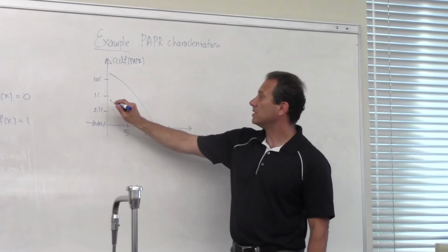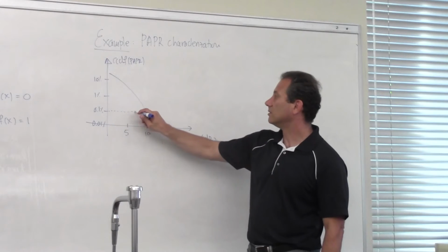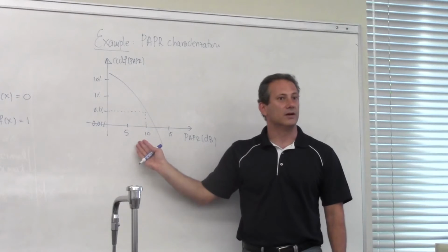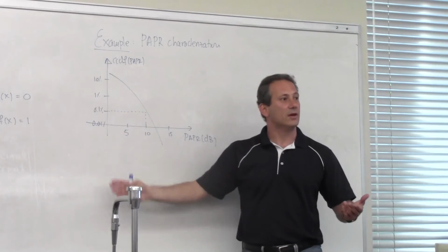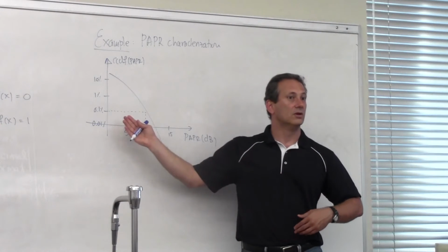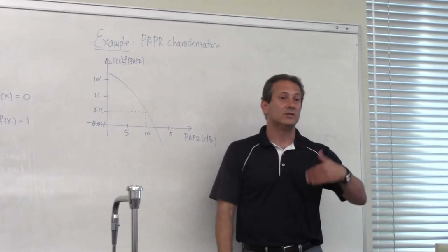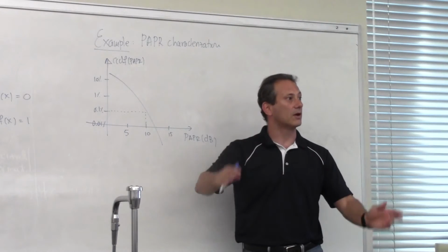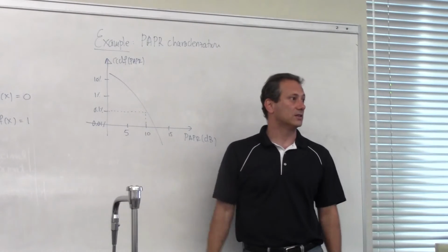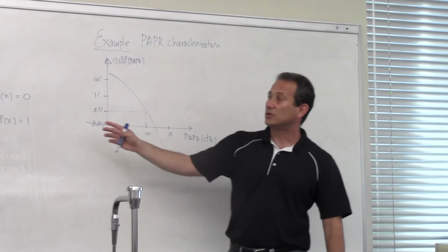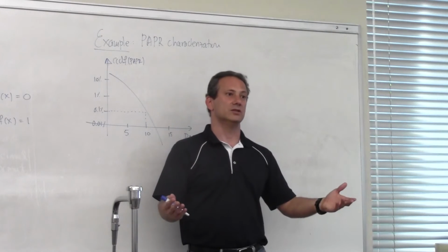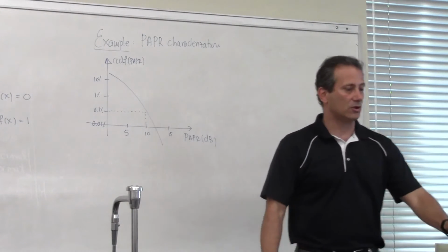So if I design my system with this threshold, then I have to back off my power amplifier by 10 dB, right? And then I know that 99.9% of the time I'm going to be within the linear range of my power amplifier, and I have to worry about it 0.1% of the time, whether it's significant, what do I do about it, do I clip before I amplify, and so on, right? But I have to find a solution for that, and what kind of effect does that have on the overall system. We're going to be talking about CCDF curves when we talk about probability of exceeding given margins. And this will translate directly into this story.